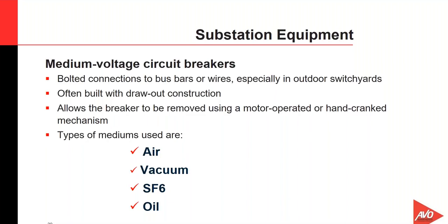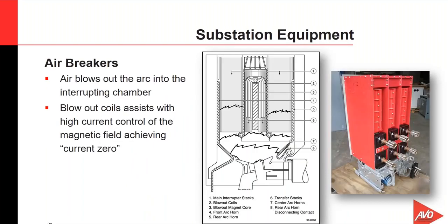So a little bit about air circuit breakers. Okay, an air circuit breaker is a simple construction. There is going to be a main set of contacts, an intermediate set of contacts, and then of course an arcing set of contacts. Within your arcing contacts, those are going to be the contacts that make first and break last.